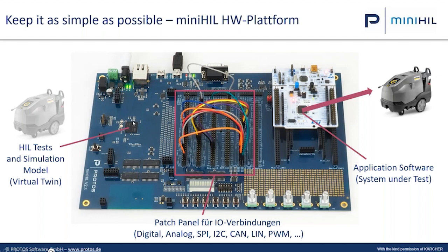And on top of that, we do the test cases, because, for example, if you have a motor you need to control and the motor is not attached, your system doesn't even get to the state where you actually can test something, because it fails before. So you need environment simulation, for example, the motor simulation, so that your system actually works. And then you can start to produce test cases.